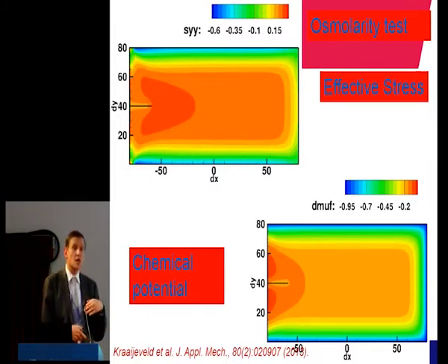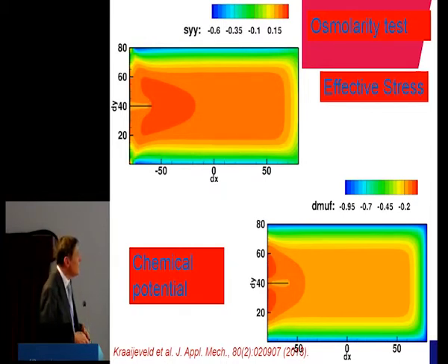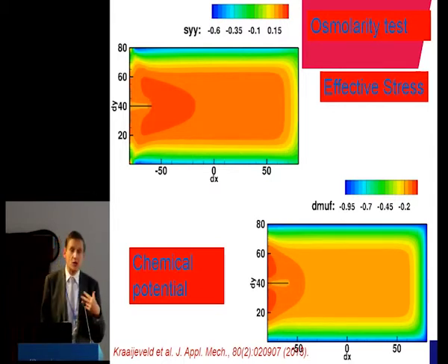You get propagation, and again, you get a protective effect of the fluid and transfer of force from the fluid to the solid, etc. In this way, progressively, the fracture goes forward, and each time you get this fluid flow going on to redistribute the load from the fluid towards the solid.